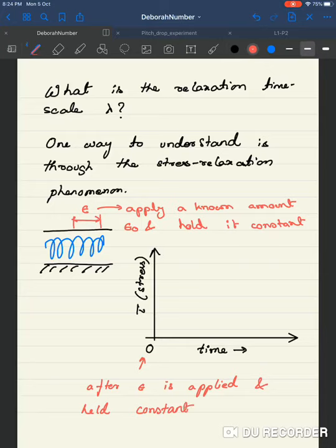So once it is held constant, what is going to happen to the stress? If it is a fluid, you've already created whatever strain you had to, so in the case of a fluid, the stress has to decrease with time. But not so if it were a solid. I have not told you what material is inside, right? If this material were something like a perfect, idealized solid, then to hold this strain at epsilon naught, you will need a constant stress.